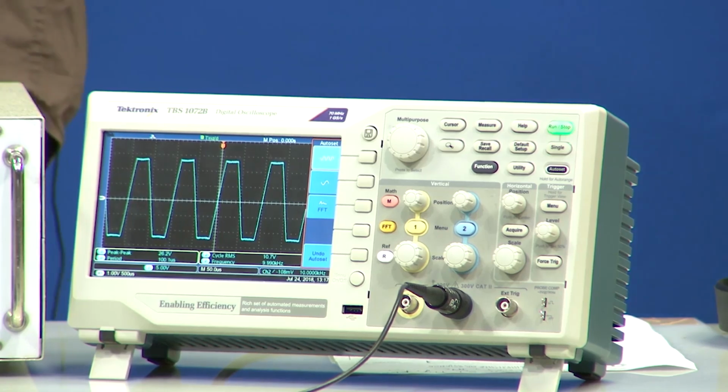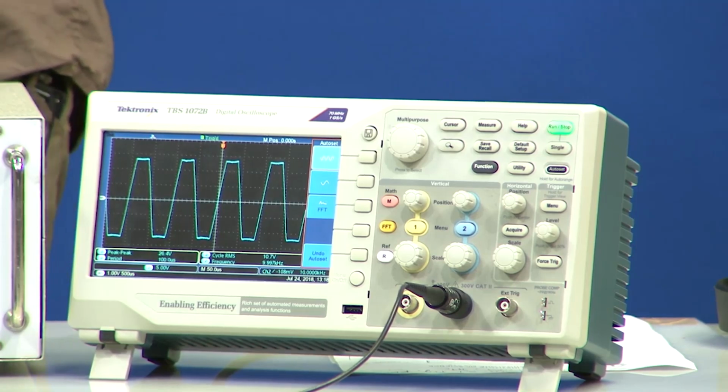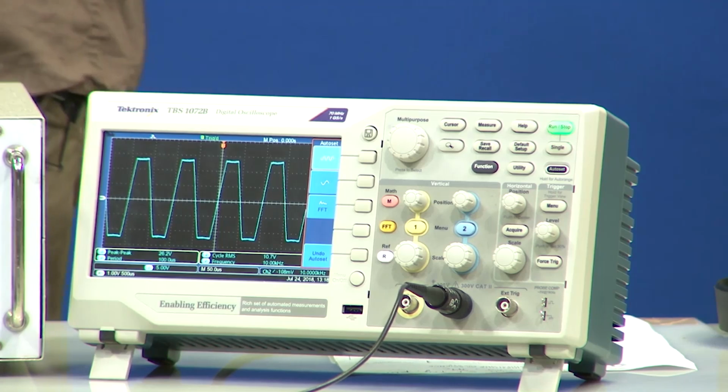Now, from this experiment it is very clear that the range of the op amp is determined by the gain that is given on the op amp, correct. So, for us to get maximum range, what should be the gain? The gain should be unity, correct. So, we will see now what is the operational amplifier with unity gain.